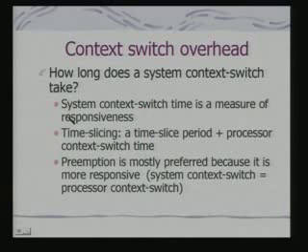In fact, if you remember ARM architecture, when I talk about FIQ, we had a copy of the registers. So under those conditions, when we are doing a context switch, that many registers need not be saved and loaded. I have a fresh copy of them, and therefore for that mode or that hardware signal, the response time will be much less compared to other modes.